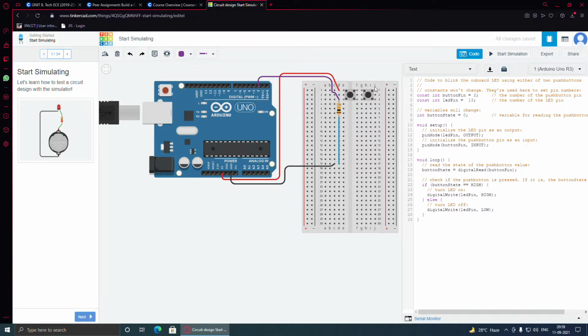In a breadboard, as you can see, there are many rows and many columns. The rows are numbered 1, 2, 3, 4. Let's say this is row 7. Row 7 has 5 holes. Similarly, these are columns F, G, H, I, J. Column J also has many holes, or connection points. In a breadboard, all the 5 holes of each row are interconnected.